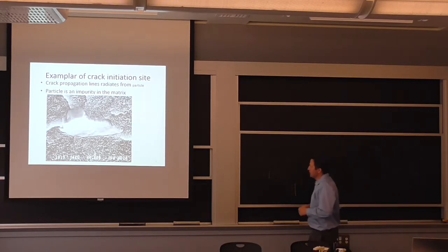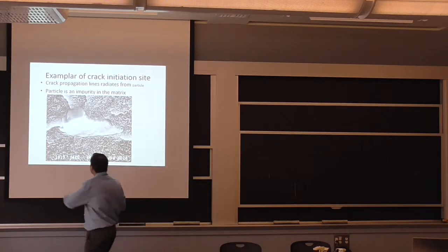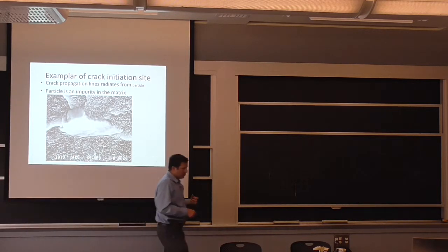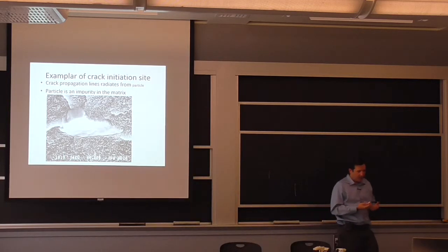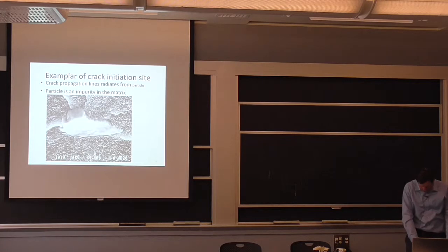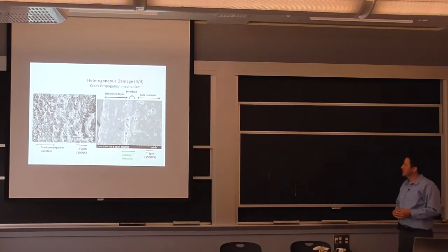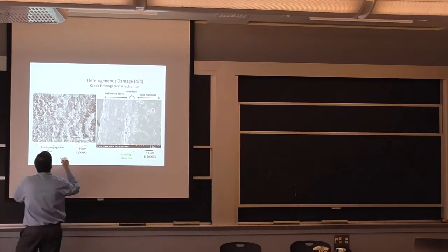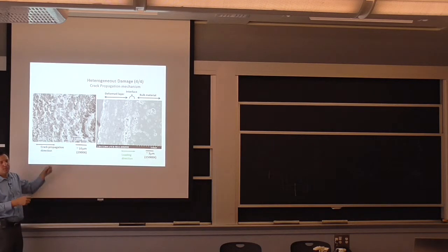The other thing here that I want to point out is how fine all this microstructure is. These microvoids that were created, these are traces, and they were created very, very slowly. But it's not only that I see these traces and there's void formation that activates. This is not the only thing that happens. So for the same material, what I want to show you here is an example where on the surface you see all these fibrils. It's all very small ligaments. The reason it's white here is because it's at a very sharp angle. This is an electron microscope image.